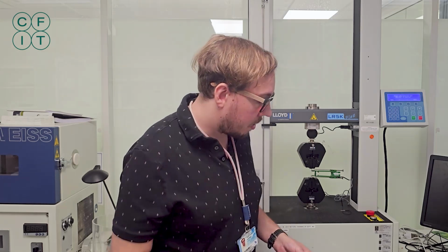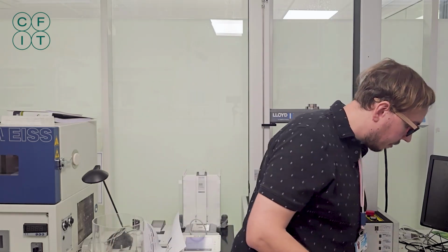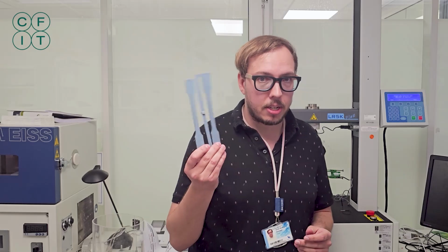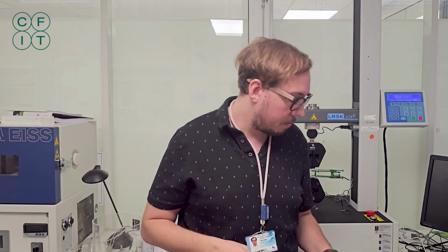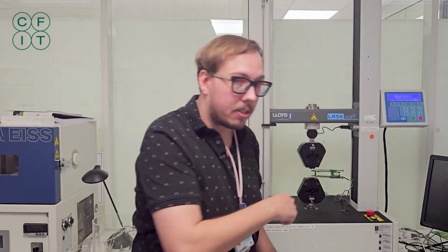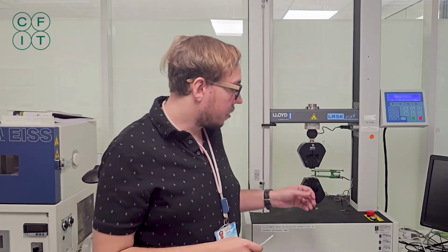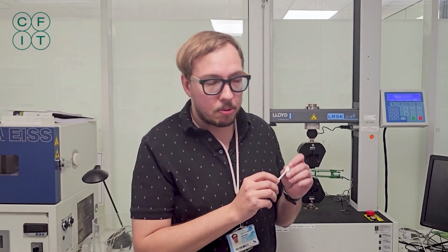So we did extensive studies, both material characterization with these ISO dog bones you've probably seen a million times, and then also we have an example here on the machine. This is an exploratory test, with these smaller dog bones that have custom geometries to give us better simulation data fit for our products. The ISO is very nice to understand what is happening on a general level, but we also have our own custom internal tests to allow us to get more accurate data for our simulations, to also show on a simulation level that this is safe.